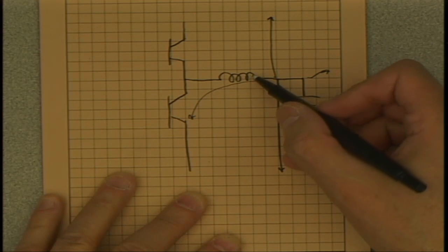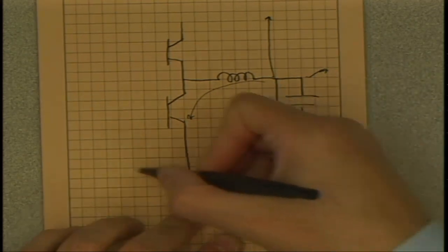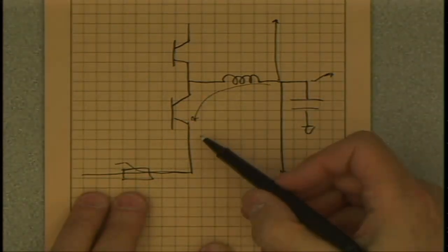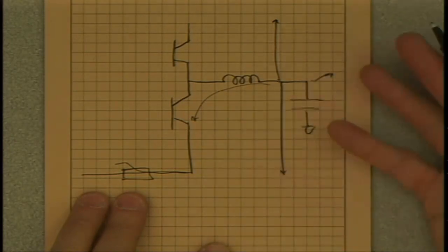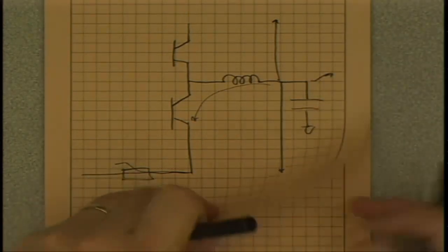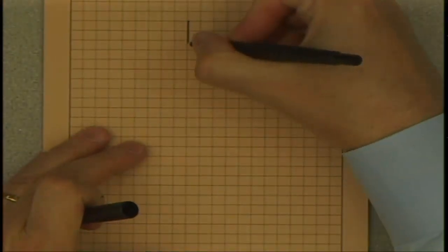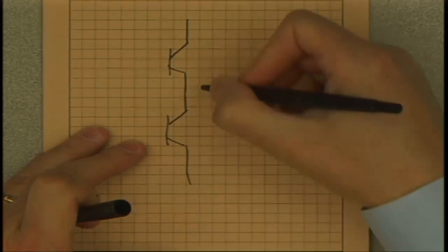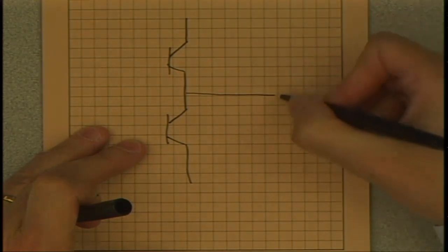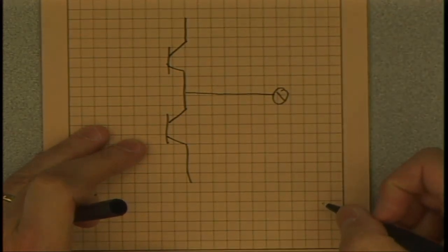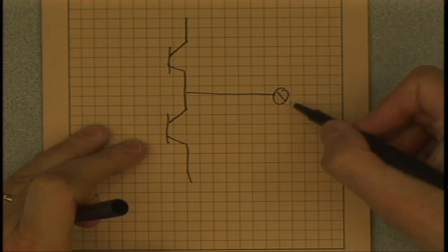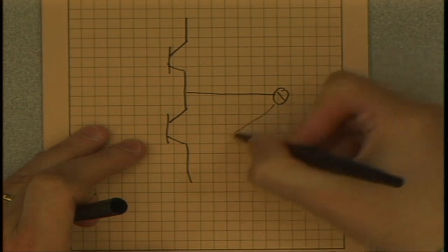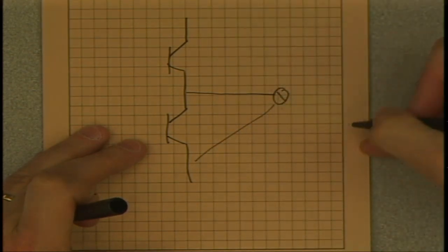The inductor buys time, so I usually have current sensing somewhere, back here in the circuit, some kind of a resistive shunt. I'm measuring current and I can detect that there's a problem and do something about it, right? But in the case of a motor drive, typically the inductor is the motor, right? And so on the drive, there's no inductor. This goes to the outside world to a big screw terminal that someone can misapply and get a screwdriver across. And so you can end up with a short either to negative bus or positive bus or earth.